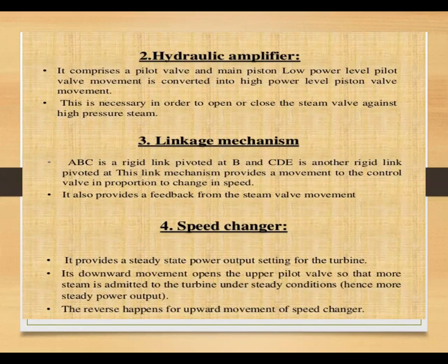Speed changer. It makes it possible to restore the frequency to the initial value after the operation of the speed governor, which has steady state characteristics. A small downward movement of the linkage point A corresponds to an increase of delta P C in the reference power setting.